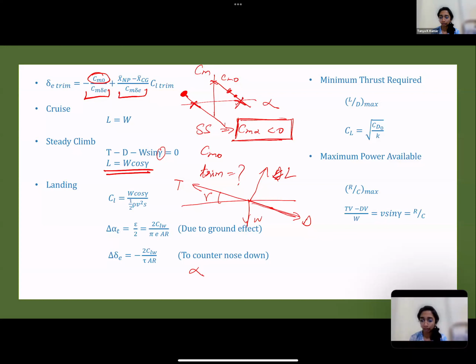What is alpha and how is it defined? Alpha is angle of attack. How is angle of attack defined? With respect to wind flow. Yes, what with respect to wind flow? An angle has to be defined by two line segments, right? What are the two line segments? One is the wind flow, as in relative velocity, and the other is the chord line, with respect to wind flow.